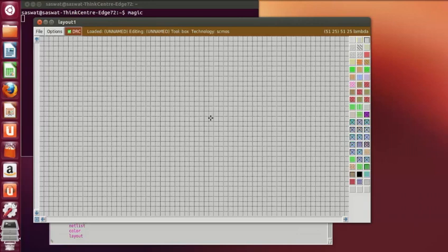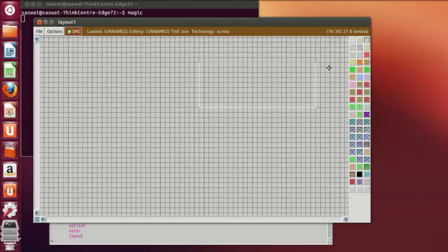the layout from the untwisted schematic, we can draw the gates in this form, the N-well, then the P-diffusion. According to our untwisted schematic, we'll draw the N-well in this form. Now click on N-well.